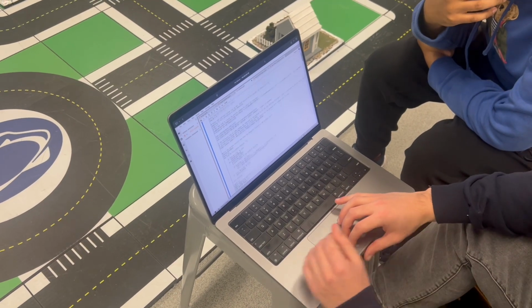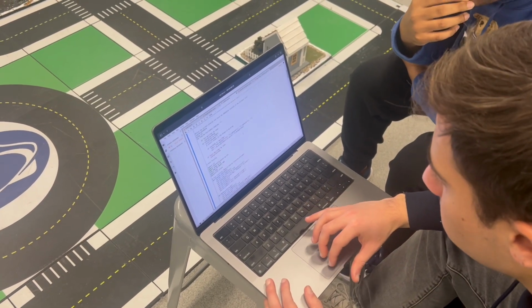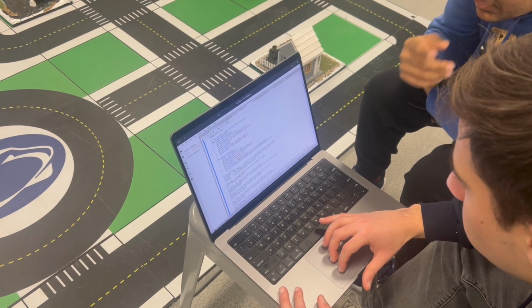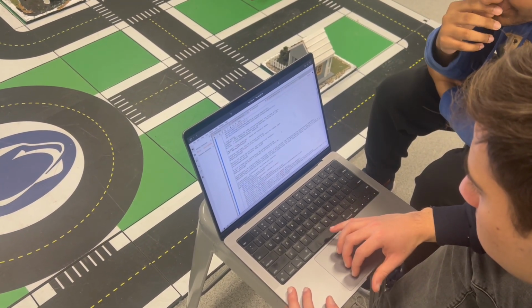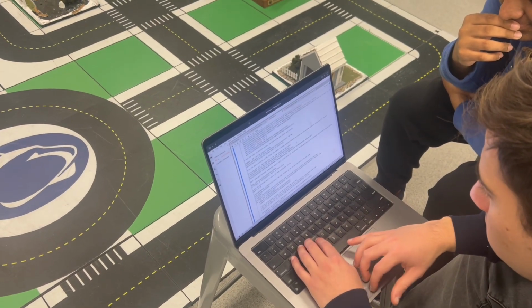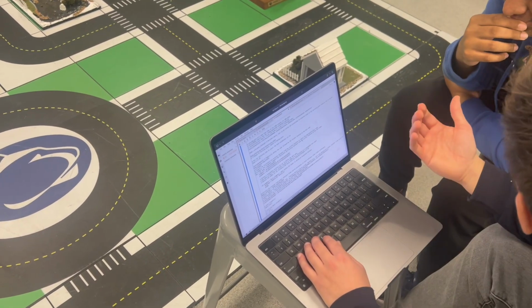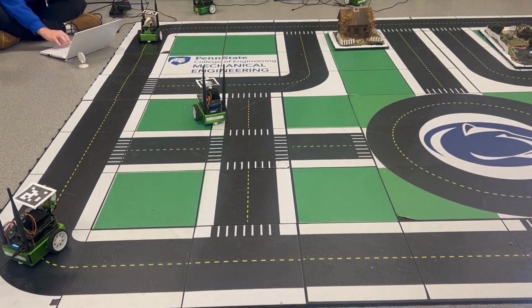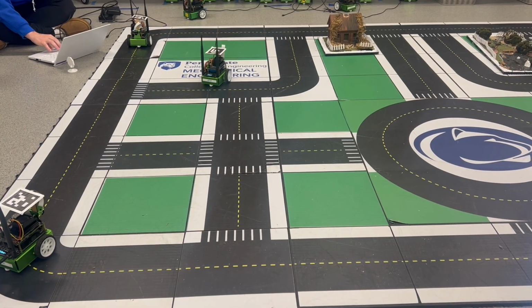After we knew what to do, we started working on the code. First, we decided to start with the basics and completed the code for the April tag and set up communication with the camera bot. Once we got the picture of the map and real-time location working, we moved on to path planning. Our goal was to ensure that the path planning prints out the shortest path for any end location using the binary occupancy grid and the node population, while ensuring that the directions it spit out were the right ones. After path testing, the next step was making the JetBot follow the path calculated.